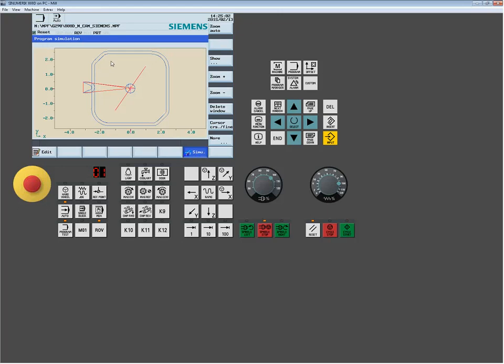So it's very important to start to understand how these commands build and understand that depending on the technology of the machine I'm on, they may function very differently. Okay, so what I really wanted to start to show you here, and this is very common when dealing with a posted program where they're compensating for the tool radius already. Let's run this. So right now, I have the tool offset, tool 1, set up at a 0 cutter radius. So this would be the actual cutter path I would need to cut this part accurately.